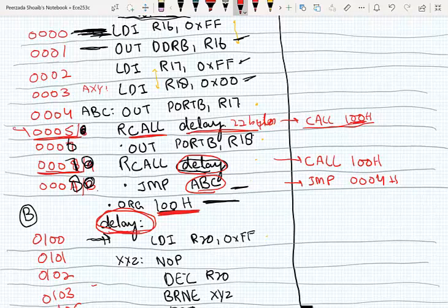and only 12 bits are used for the address. 12 bits translate to, that means it can be either from -2048 up to 2047 memory locations. That means it can be within 2048 memory locations from either side from where I am calling this subroutine.